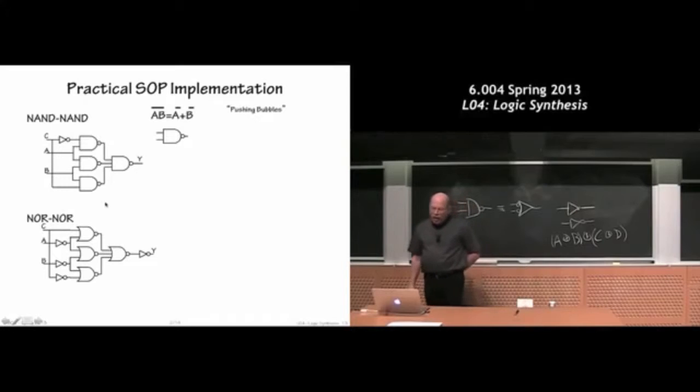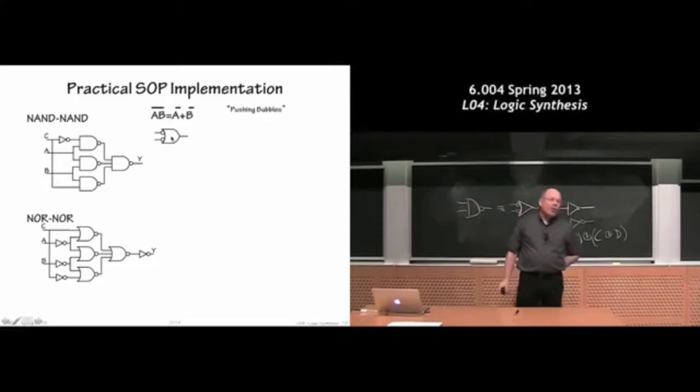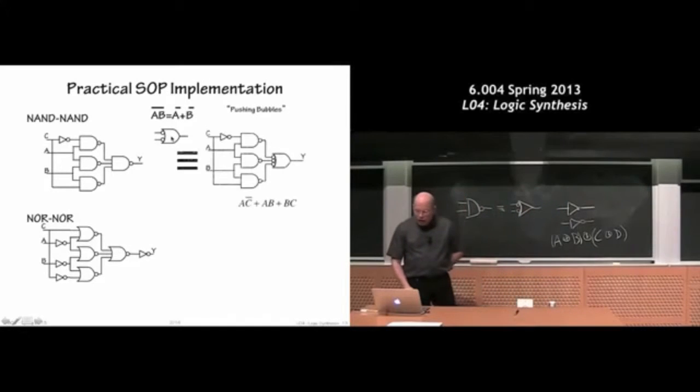And so I'm going to use this notion that a NAND converts into an OR of NOTs. So a NOT of AND. See what I did is I redrew that symbol. You can see the little animation there as I change it from a bubble on the output to a bubble on the inputs. And as the bubble passes through the body, it converts ANDs to ORs and ORs to ANDs. So if I take this diagram over here, you can see what I've done is I've redrawn that 3-input NAND gate as a 3-input OR gate with inverting inputs using De Morgan's law.